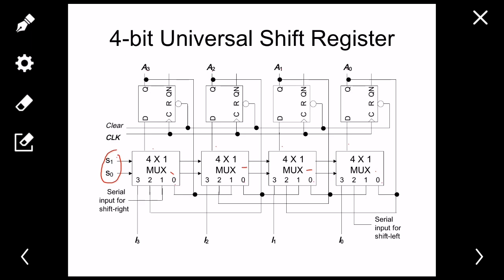So what we can do, we can take the present output, that is a3, for this bit. We can take this, and we have seen that we have connected it with the 0 number pin. So what is happening is, when we are putting 0 0 at this point, this pin is activated, and the a3 from this path moves towards this path, and it goes to this path. And after a positive edge, this value of a3 moves towards this output, so the output doesn't change.